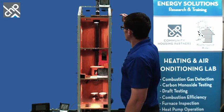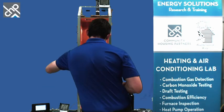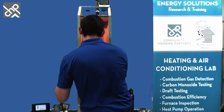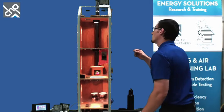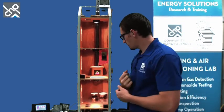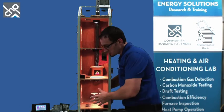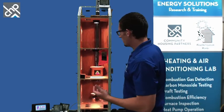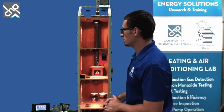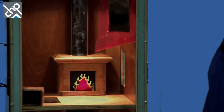Turn that off. Got a little fireplace here in Grandma's house. Fireplace. So take my damper off. Need that. So this is Grandma's house, sealed up. I've got the crawl space door closed. I've got the attic, everything's sealed up there. My exhaust fan is turned off right now, it's unplugged. And lo and behold, what do you see? So this fireplace, when it's running, is actually drafting properly. The smoke is going up and out in its intended direction, as we would expect.